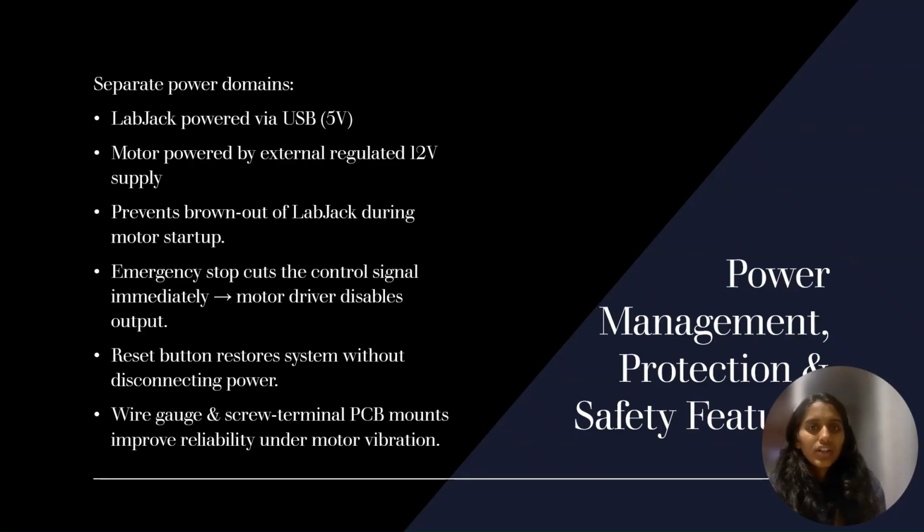If both share the same power, the lab jack could crash or disconnect, so we used a completely separate 12 volt power supply for the motor. This prevents brownout issues and protects the lab jack. We added two safety switches: emergency stop, which instantly cuts the signal so the motor stops immediately, and the reset button, which restarts the system without unplugging anything.